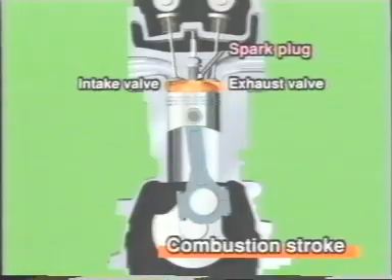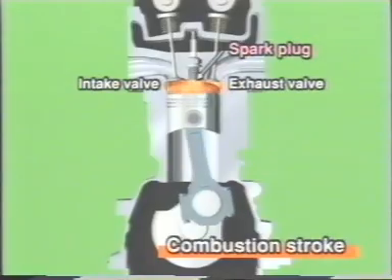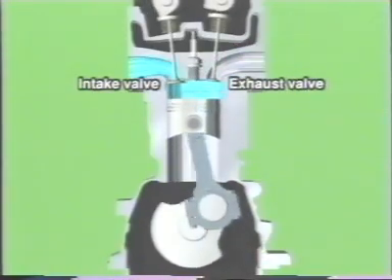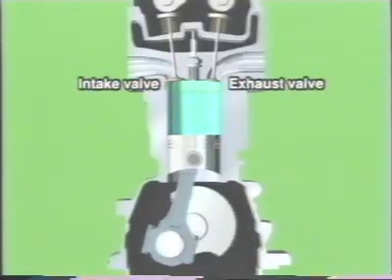When the piston almost completes its upward stroke, an electric current applied to the spark plug causes it to spark, instantaneously exploding the air-fuel mixture. This explosive power pushes down the piston, causing the crankshaft to rotate. This is the driving force of the vehicle.